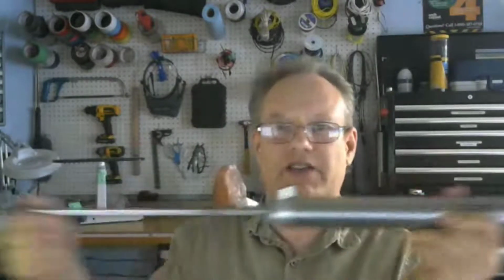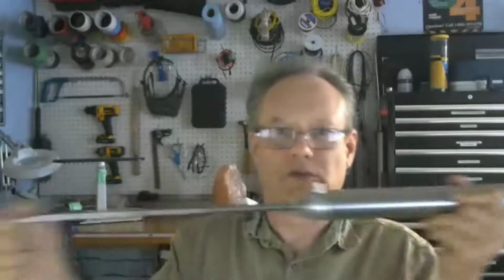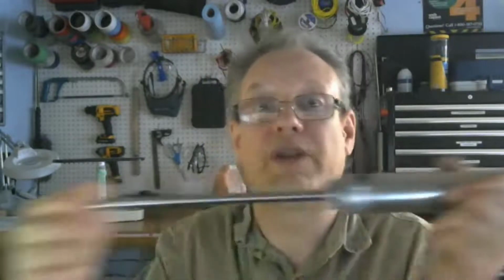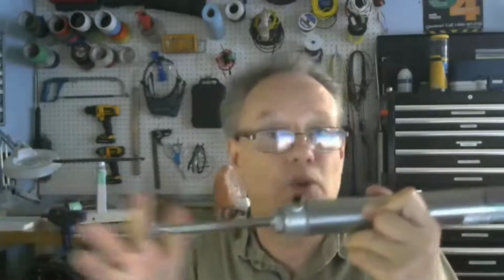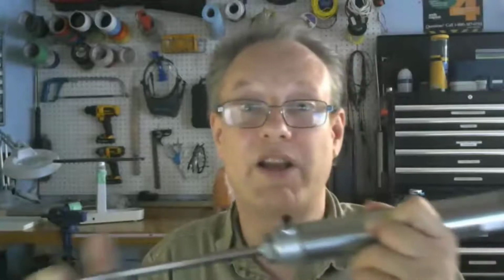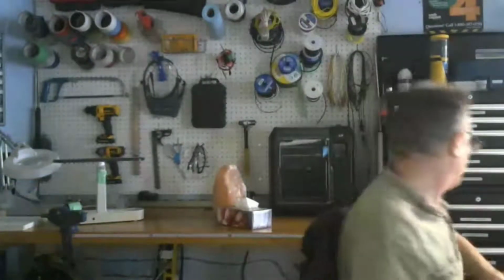So if this is going like this, how many times is that going to happen in a minute? Well, if I'm doing it once a second, it's going to be 6 cubic feet or something. It's going to be some larger number. If I'm doing this slowly, and I do this so many times in a minute, and they have 3 of these or 5 or 6 of these in a system going, and I have 1 compressor running it, well, the total amount of volume displaced in a minute is going to be in cubic feet, even though this is just 0.1 cubic feet. So yeah, when we talk about flow rate, when we're after the flow rate of pneumatic